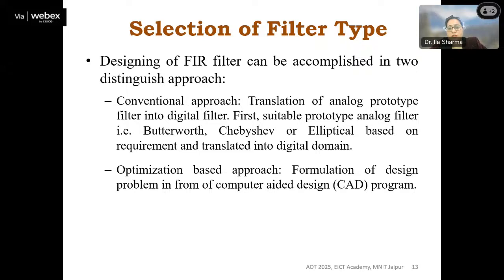Windowing is also very tricky, because we have different types of window functions, and according to that, we can fetch our spectrum. You heard about the Blackman window, Kaiser window. There are so many windows, each with its window function.